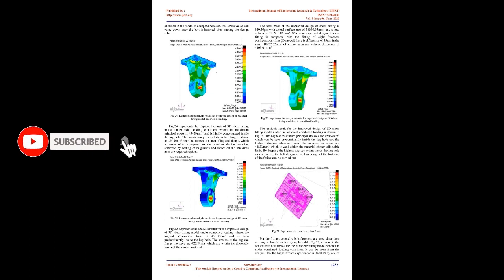21 caused a decrease in the stress concentration near this region, and a higher concentration of stress is observed inside the lug hole. Though the allowable tensile strength of chosen material is 428 N/mm2, the stress obtained in the model is accepted because this stress value will come down once the bolt is inserted, thus making the design safe.